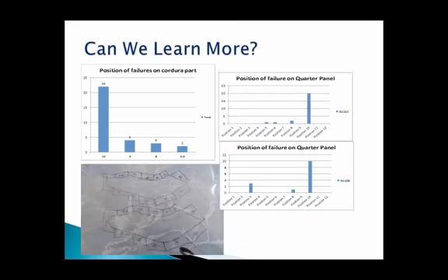Okay? One thing I always prompt people to do is to actually dig deeper. So you have some data, but what's the next level? How much more information could you get if you put some effort into it? In this case, they created a nice little tick sheet. These are the cutouts of the material of the boot, and they wanted people to put ticks where the issues were happening and write a little explanation, and they gathered that data, and it gave them even more information as to where the root cause could be.